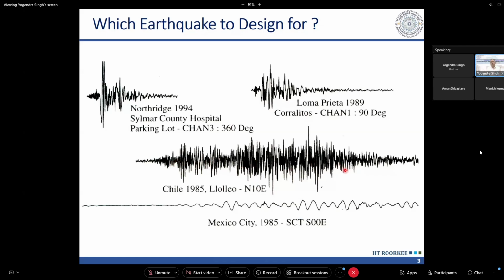If we are talking about fatigue, where the surface load is causing fluctuations in the stresses, that is also causing some damage in each cycle. And if the damage gets accumulated for millions of cycles due to fatigue, we get the failure. In case of an earthquake, what we get is low cycle fatigue.